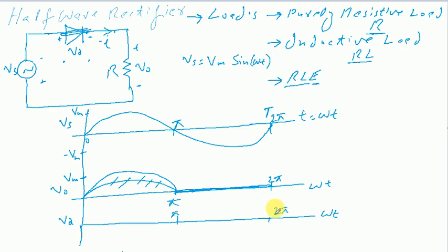It is very simple. During the positive half cycle, as I mentioned, we are considering an ideal diode, so it will be behaving in the forward bias mode and will effectively be a short circuit. There is zero potential developing across any short circuit device. So we will have no voltage appearing across the diode during the positive half cycle.